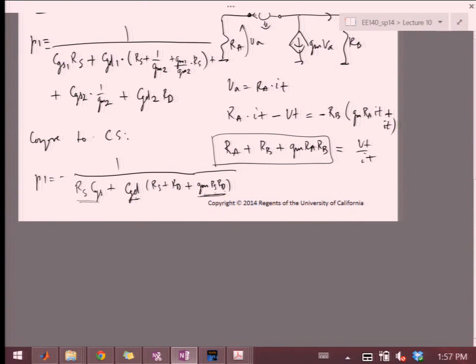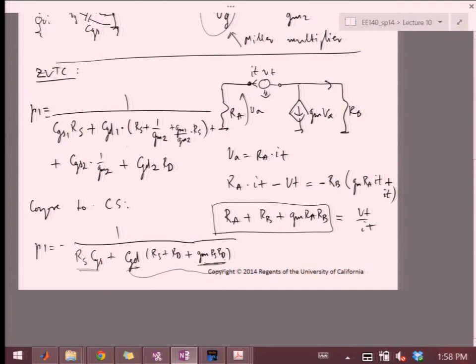And that's why this now becomes not insignificant, because I'm comparing my CGS to CGD multiplied by the gain of the amplifier. So with higher gain, that input bandwidth is going to be very limited. Now here, I don't have any of that, because I just have RS, because these two are pretty similar. This is my Miller, so it's very small. And then at the output, again, I have CGD times RD, so there's no multiplier. But my intrinsic gain is GMRD, so I've sort of decoupled gain from the bandwidth a little bit in this case.